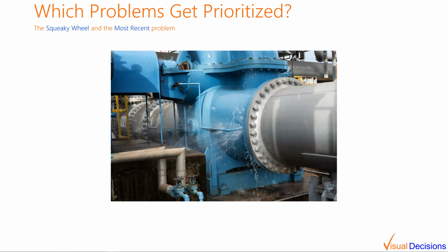There's a story here that I like to tell about a shampoo manufacturer that I worked with a few years ago, where they had an overhead conveyor that fed the filler of their operation. And in the data, I noticed that the filler was going down like every 20 minutes or so. So I went out to the line to see what was going on. And I noticed that very often the overhead feed would jam up, and eventually the filler would run dry because they couldn't fill any bottles anymore, and it would flash an andon light.